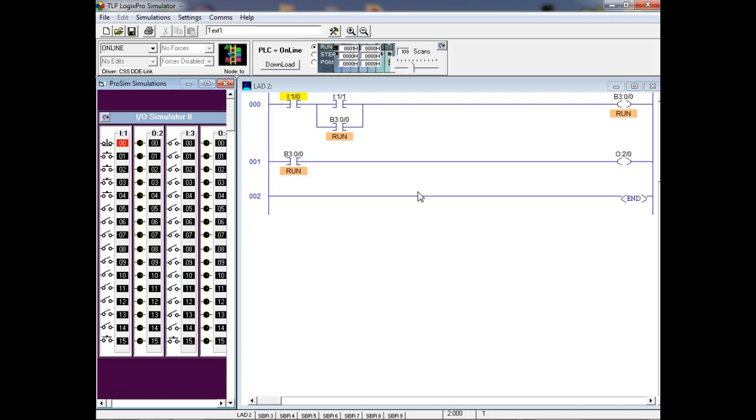No. So in motor control, when we start dealing with very complicated motor control, 90% of the control circuit is decision making. And if I don't need a relay to generate an output, I'm not going to sacrifice an output. I'm going to use an internal relay.